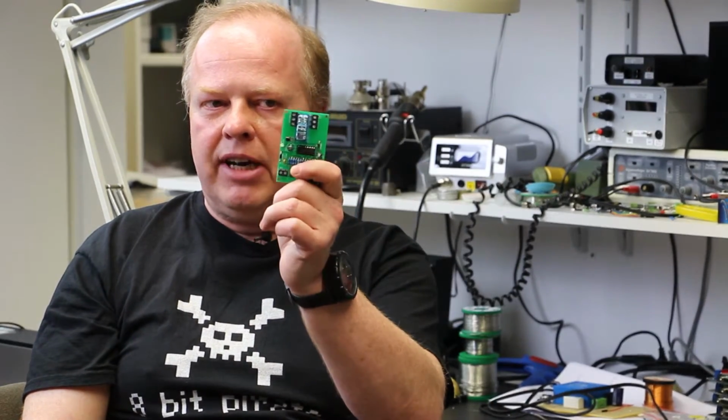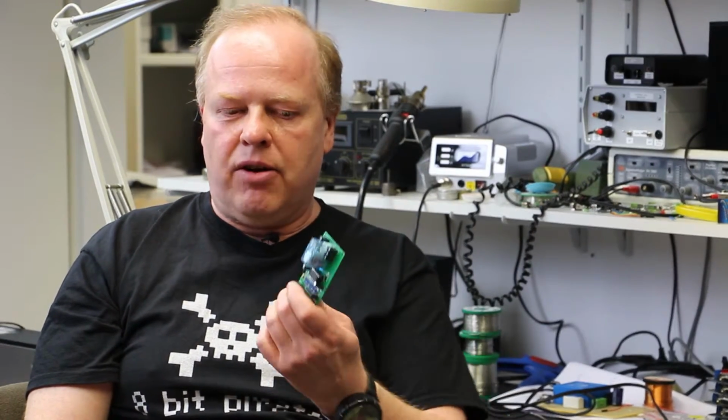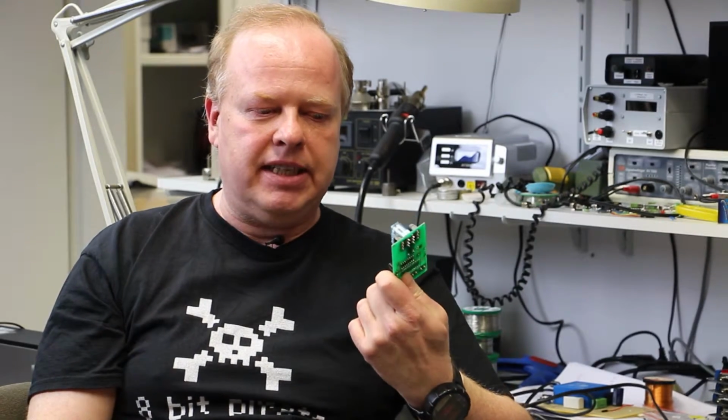And I give you some advice because we use a power relay which can switch a mains voltage and mains current. There are always two things you should be aware of, and that is the ratings of the relay, especially the amps rating, because even if it can switch 8 amps in the case of the relay that we are using, this is not true for a DC voltage, and this is not true when you switch reactive loads.